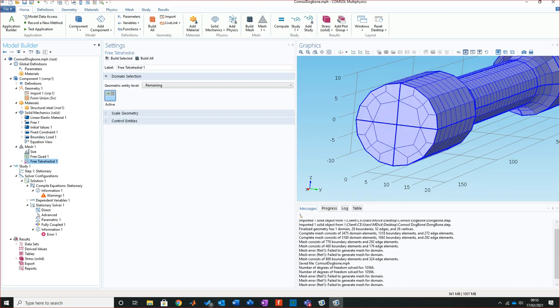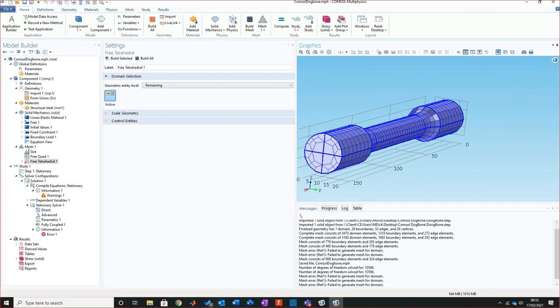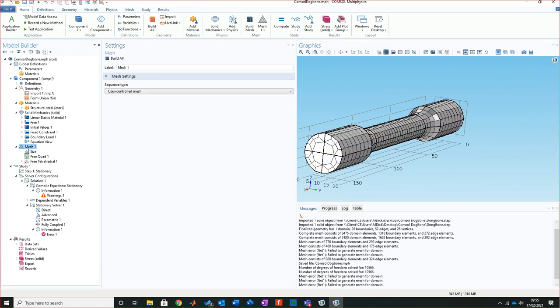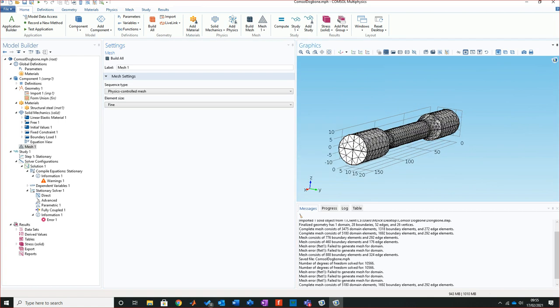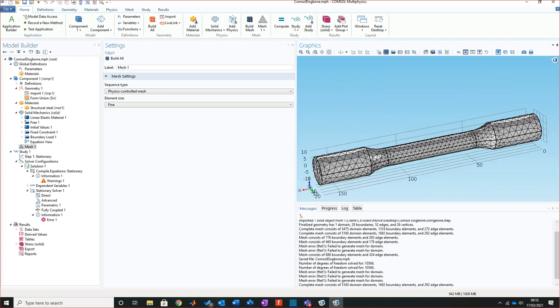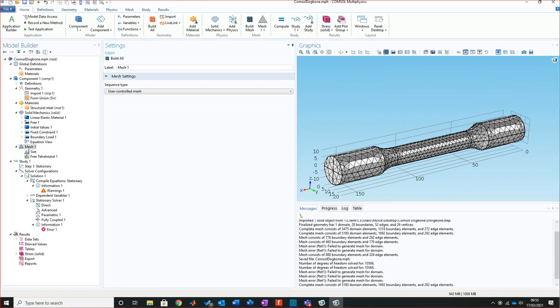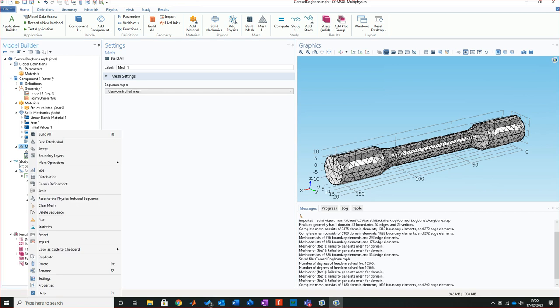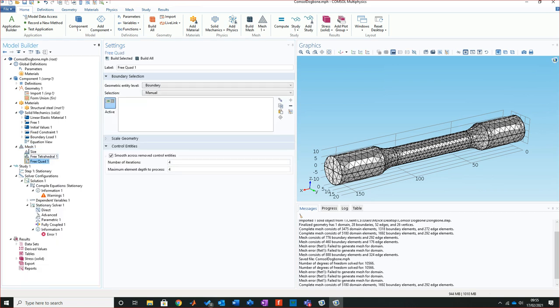Now, what it's complaining about is that part of the meshing on here hasn't been completed. So I'm just going to reset it by using the system-based one, like that. And then I'll come back onto here and I'm just going to try and drop in those 3 quads, and bring up my 3 quads a little bit to here.